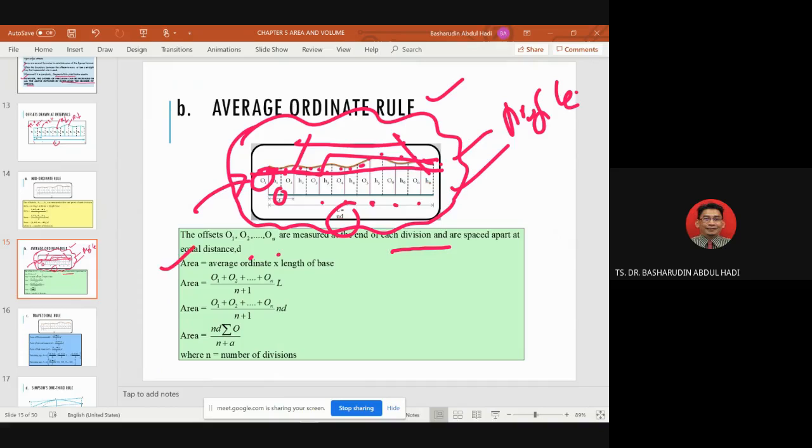Area is equal to average ordinate times length of base. The length of base, from here to here, is the distance. So the area is equal to O1 plus O2 plus up to On, divided by n plus 1, times L.